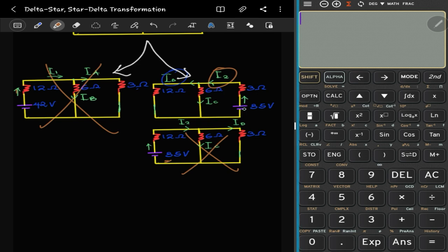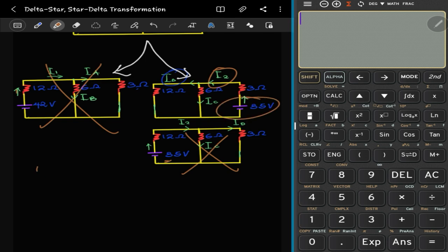And I2, from the look of things, is the current from the only voltage source, which is this 32 here, right? So V is equal to IR. Then what do we need? We have our V, we need to find our R, then we can find our I, right? So how do we find our R? Looking at this very well, this is not Thevenin, right? We are not doing Thevenin, so we just see these two elements here to be in parallel, right? So basically we have the total R. So here instead of R, you just write RT. The total R is